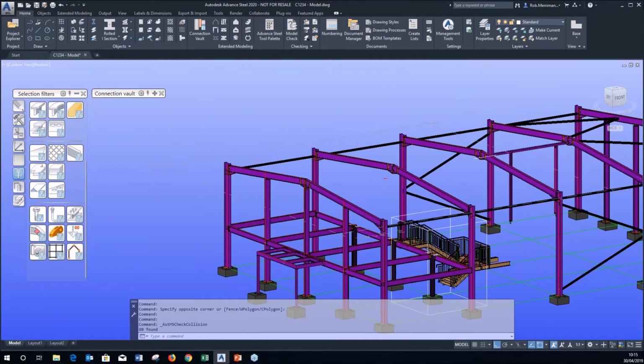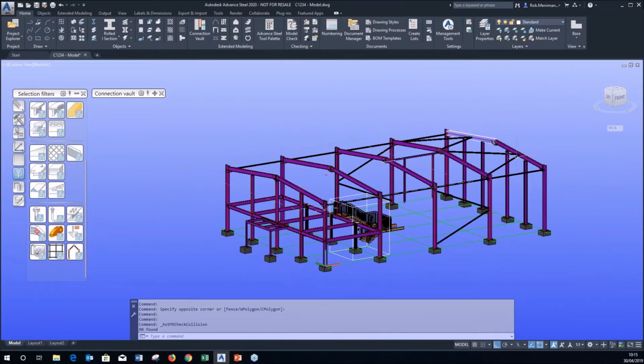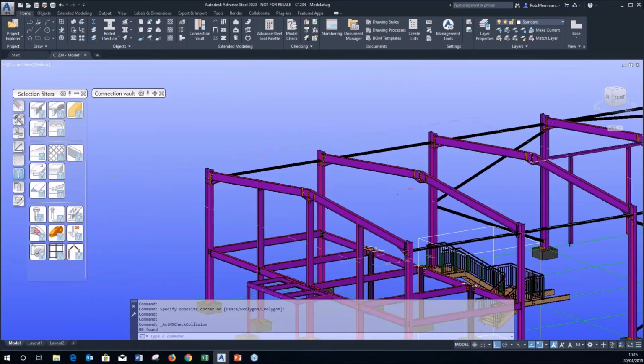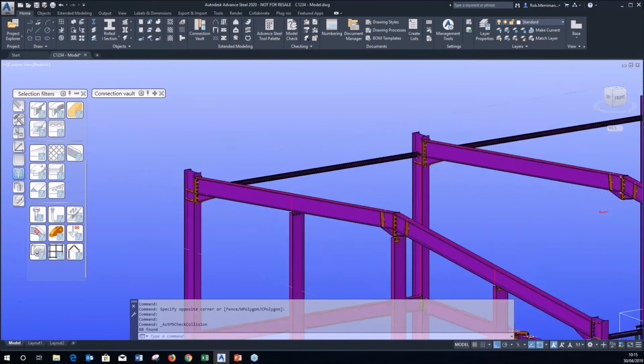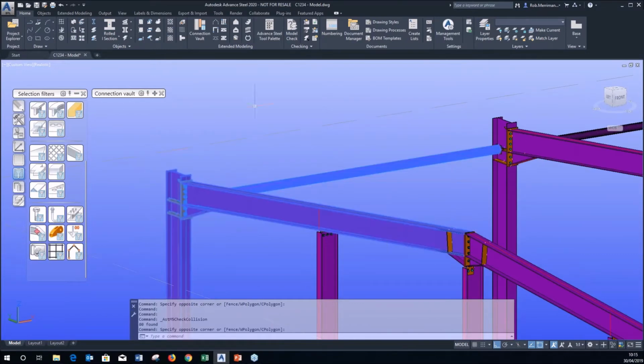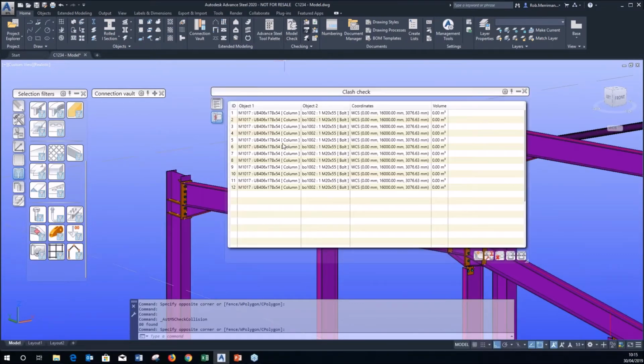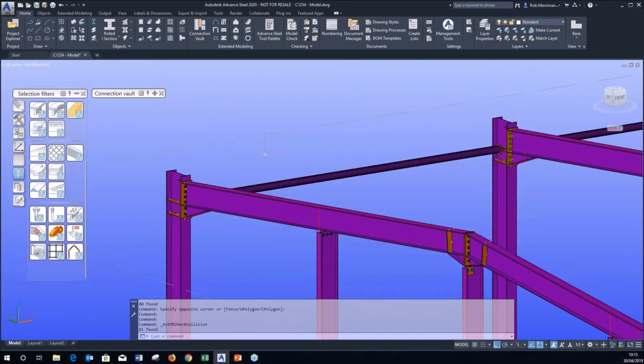And if I copy that round the building, let's say I've got 10 columns, that would be 120 clashes. Whereas if I clash checked it the first time I put it on and gone, oh, I've got 12 clashes, correct that so that I've got no clashes, then when you copy it round, you're not copying around 12 clashes onto every column. So we would strongly advise never leaving clash checking until the last thing you do.